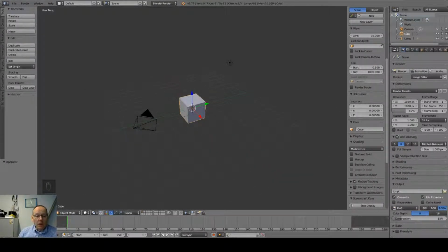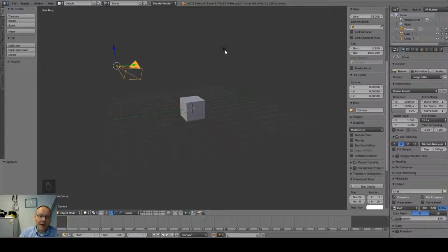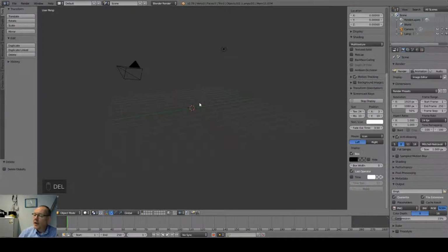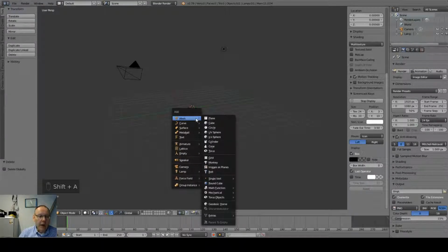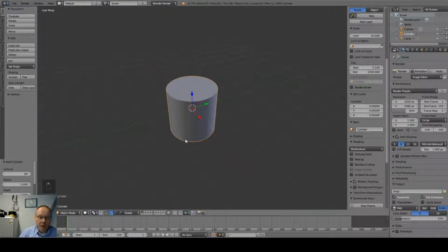So as always, when you open Blender, this is your basic view where you have the camera, and you have the lamp, and you have the default cube. I don't need the default cube for anything. I'll just delete it, and then I will add a cylinder instead. Now I need more vertices than 32, because when you print something, it can actually print circular things so that the 32 vertices will show. I'll just add 60 so that it looks more round.